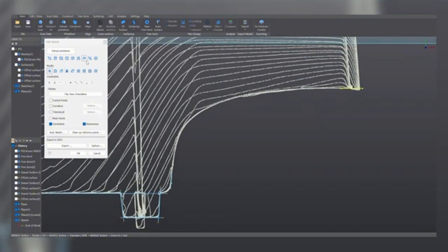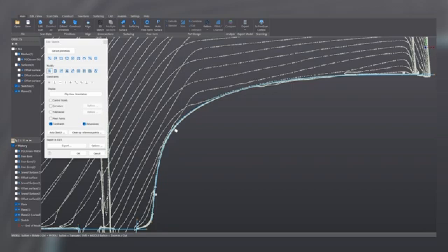Good. Now, to close it, we add a spline. We're gonna use 2 control points and close it with the endpoints of these lines. Now, because we want a smooth transition, let's make them tangents. So select first the spline and then one of the lines and click on the tangency constraint. And do the same here, spline, line, tangent. Now you can use the control points to adjust the spline accordingly. And you will get a very nice result.